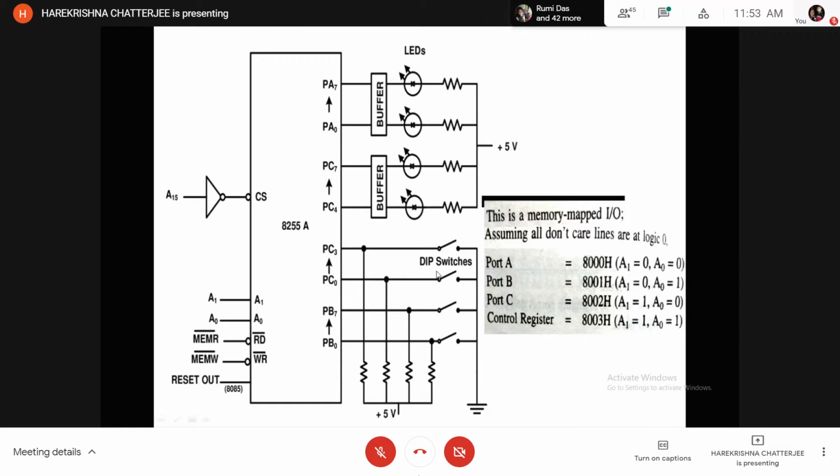How? By using rotate left instructions. 4 times I will be rotating. So this PC0 to PC3 status will then be reflected into PC4 to PC7. That bit pattern is to be loaded into the accumulator.